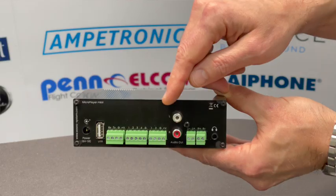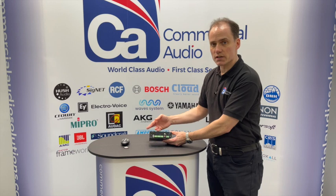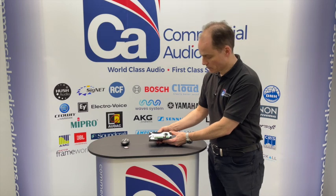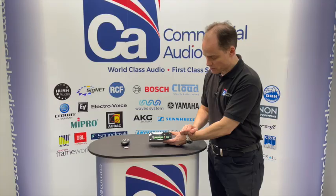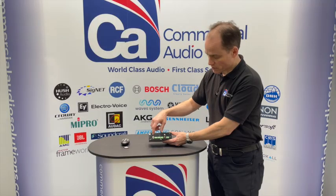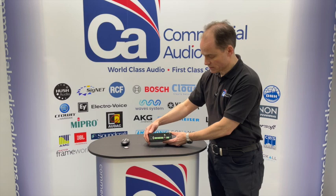We've also got 2 relay outputs which can be programmed inside the player to close when the actual player is playing a message. These will handle up to half an amp of low voltage, and it can be used for operating relays and other devices like lights and things like that. And again, we've got the speaker outputs for driving 2 8-ohm speakers up to 10 watts aside. There's also a line level output on phonos, and we've got the USB connector if you want to use a USB stick instead of an SD stick.